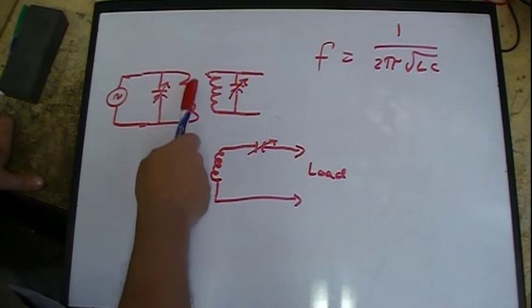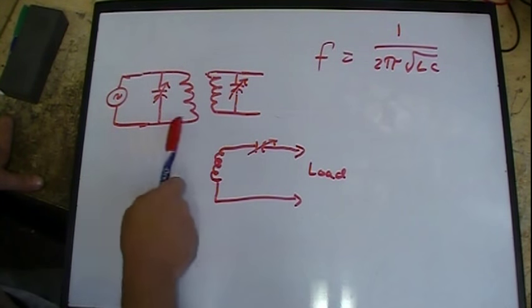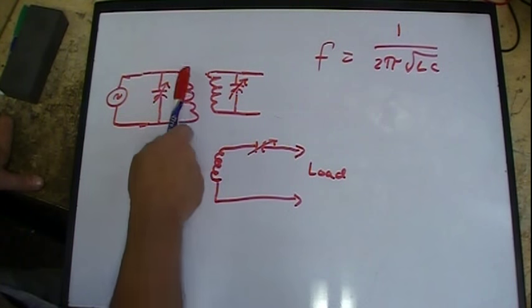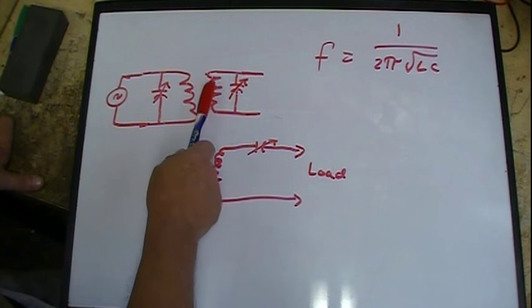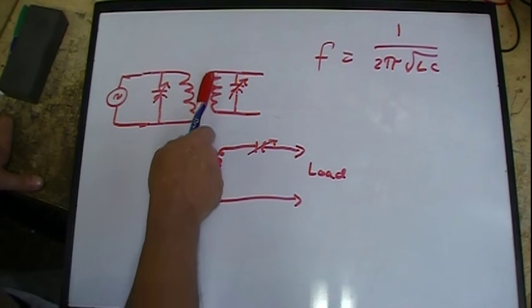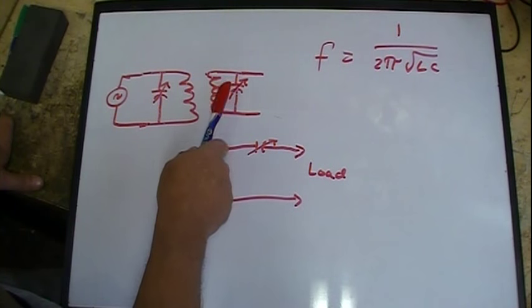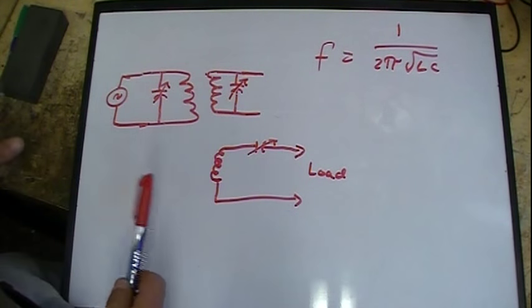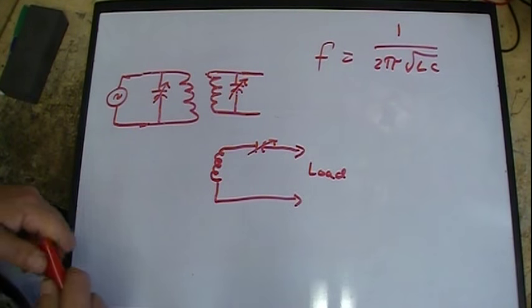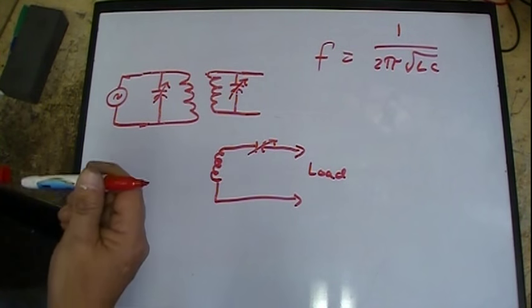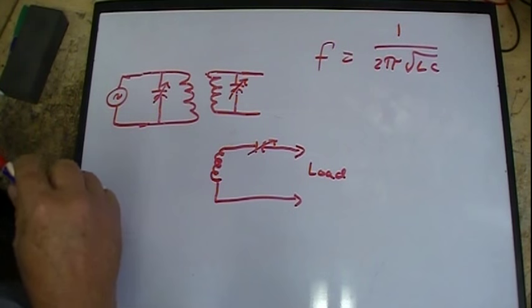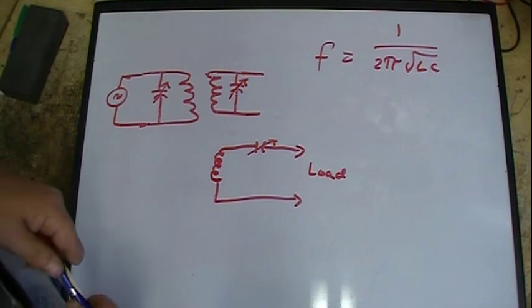So the biggest thing to understand about how it actually works is that I feed the signal to both legs here, but it's induced just in the coil and feeds out. The capacitor appears to the circuit as being in series with the coil, so it becomes a series resonant. And it didn't happen by accident.